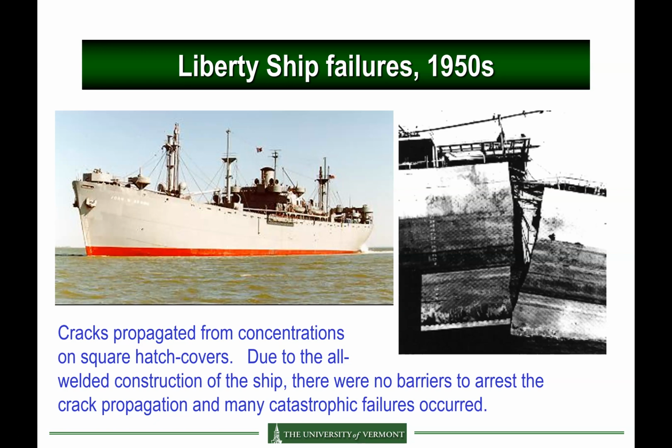The crack propagated from the stress concentration at square hatch covers at the top. And due to the all-welded construction of the ship, there were no barriers to arrest the crack propagation, and many catastrophic failures occurred. This is very dramatic here, where we can see the propagation of the crack through the hull of the boat.